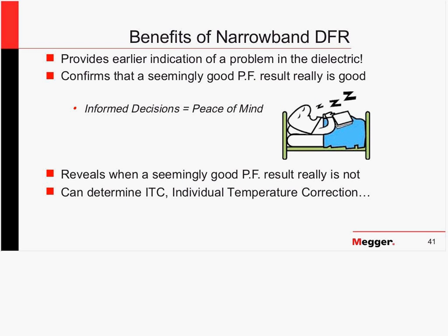I would say that it provides an earlier indication of a problem in the dielectric than we've been afforded all these years with just a single power factor measurement. And that's huge, right? So a couple of things, and I like to emphasize this one. If you really think about it, it's important. But the second one, it confirms that a seemingly good power factor result really is good.